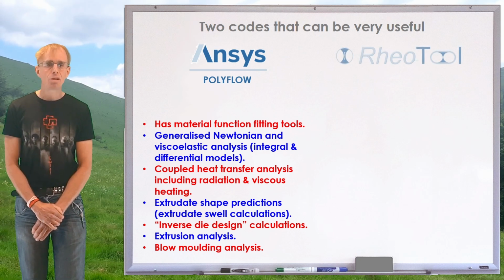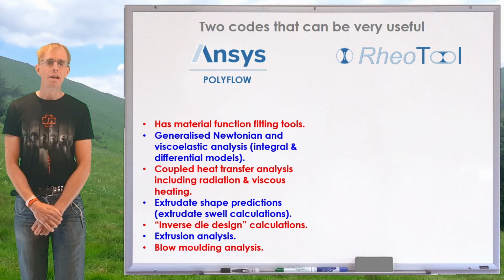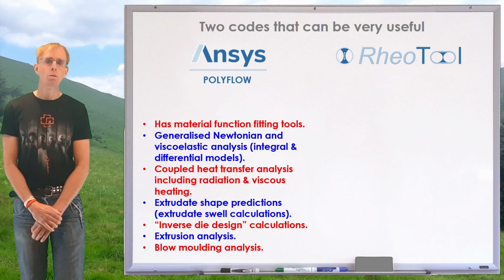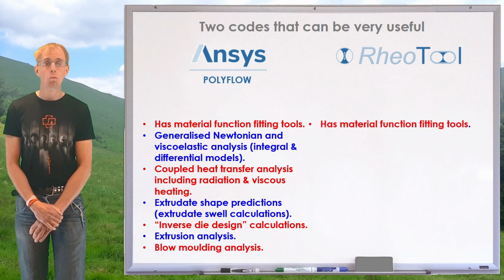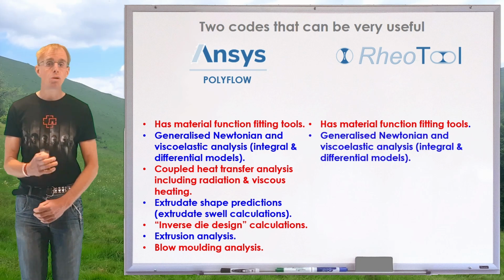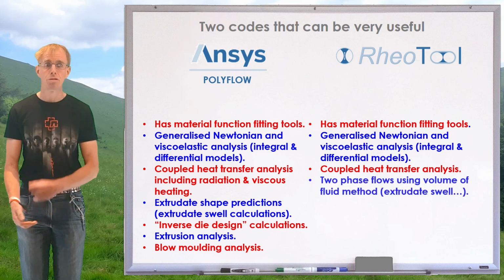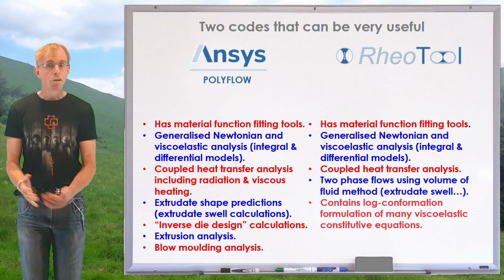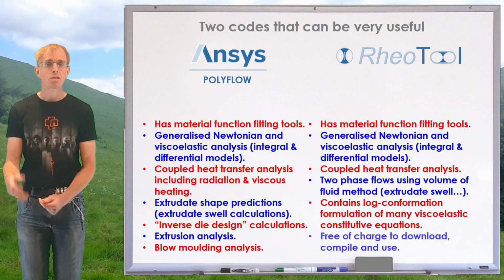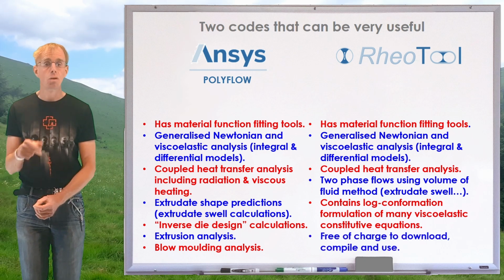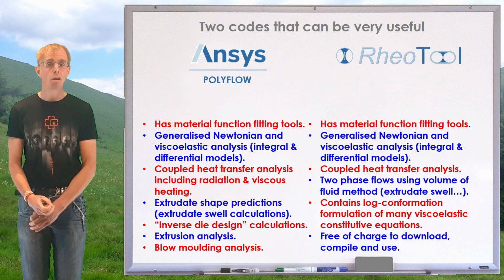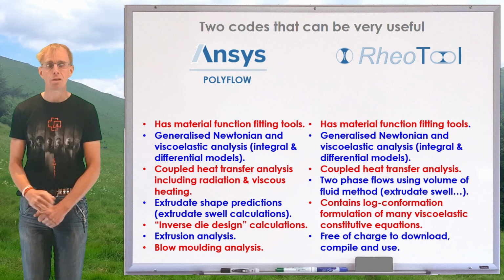Now, there's a new tool, relatively new tool, that's on the scene now, and this is called RheoTool. Now, RheoTool is a plugin to an open source computational fluid dynamics code called OpenFOAM. It's an incredibly powerful platform, and it's all public domain. RheoTool 2 has material function fitting tools. It can do generalized Newtonian and viscoelastic analysis, integral models, differential models, heat transfer, two-phase flows using volume of fluid methods, so you can get some insight into, say, extrudate swell, and contains log-conformation formulations of many of the viscoelastic constitutive equations. And of course, it's free of charge to download, compile, and use.